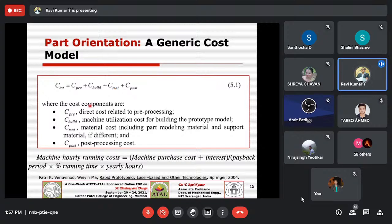So your material cost is also going to play a vital role, and it's the thing which we need to be much cautious about. And then the post processing cost, where we need to remove the support structures, clean the surfaces, sometimes subject the part to a furnace treatment, or sometimes machine it, shot peen it, or bead blast it, and that cost is also added here.